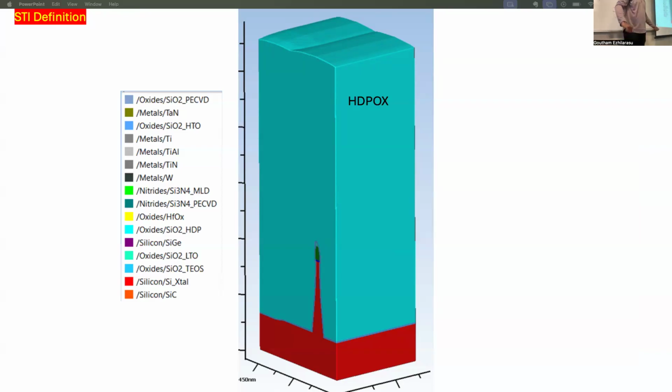Why do you make this tall? Which, the fin? The fin is the top region of this whole structure. The part of the fin that's actually used in conduction is only this part, okay? There are some reasons they make it wider at the bottom. This is a mechanical reason why they make it like that. There's also an electronic reason. For thermal dissipation? No, it's not because of thermal dissipation. Thermal dissipation is actually worse when you make it taller. It has to do with mechanical stability as well as the electrostatics of the device itself. That has to do with why it's built that way.